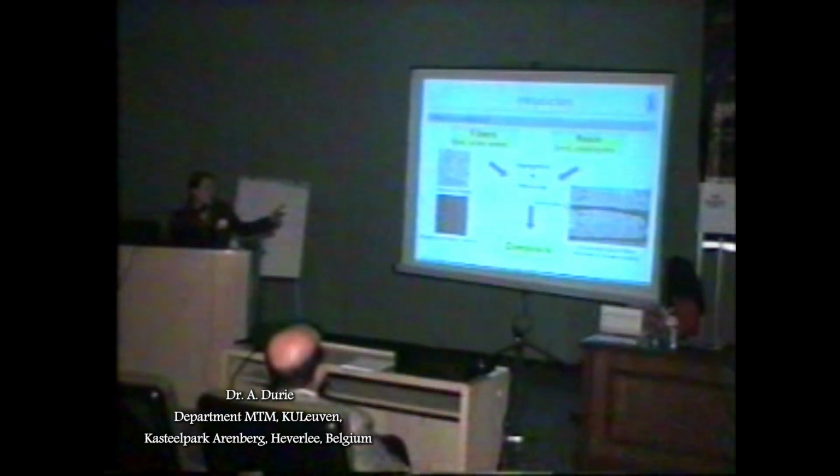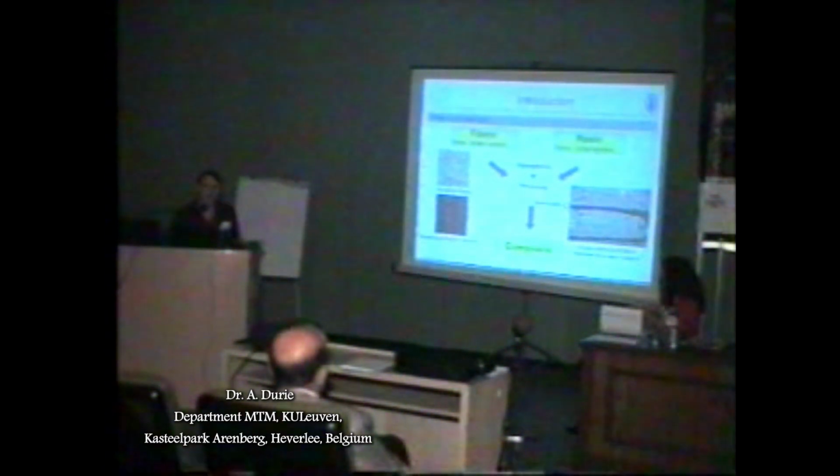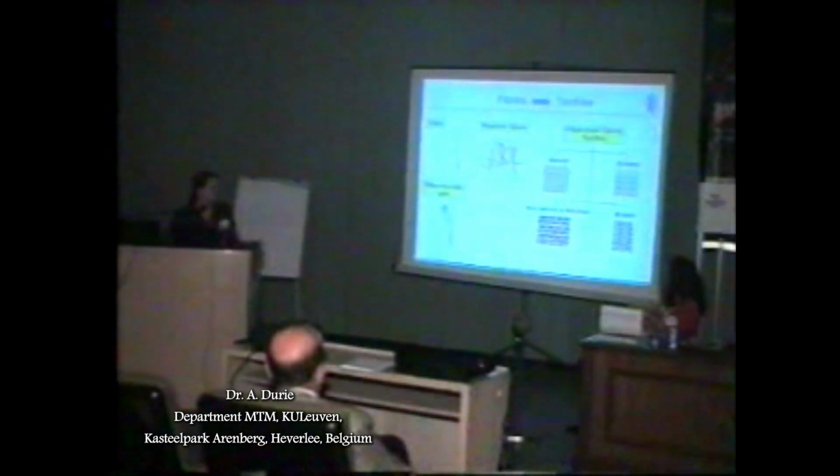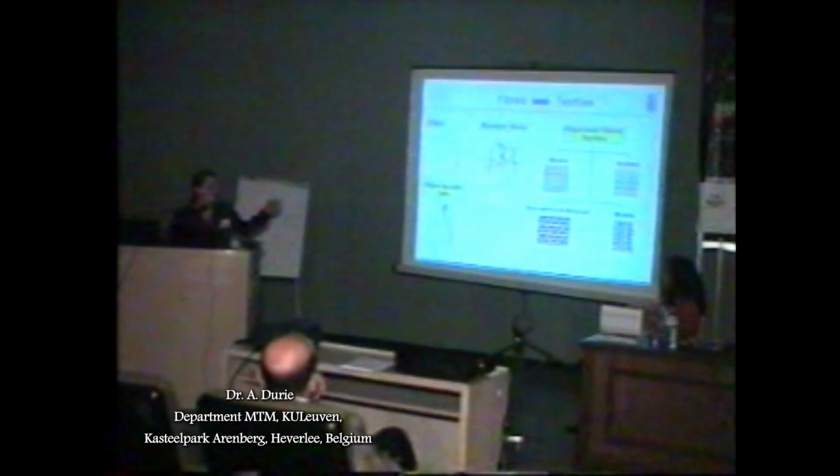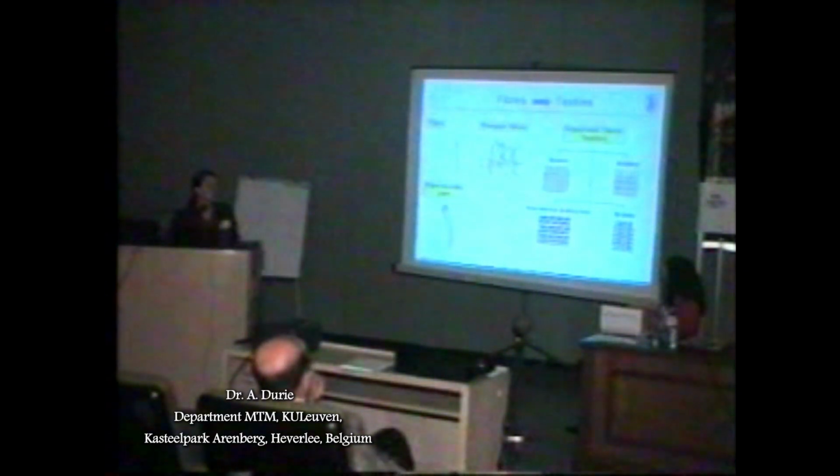And if you have a look at the arrows, they actually point to fibre bundles. So these are actually filaments of glass inside a matrix material. The matrix material is the darker part of the material. Now the properties of these really are highly dependent on the textile structure that's on the inside of the material. So for example, if you have a chop strand mat, you can use fibre bundles, or you can use more organised fibres in the form of textile, for example woven and knitted materials.